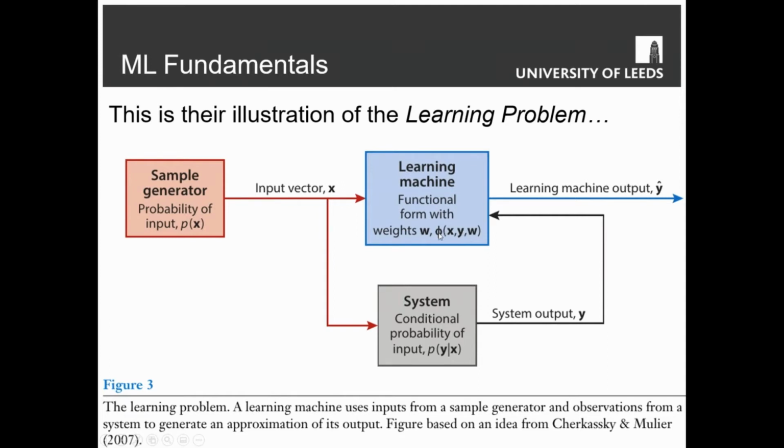And then what we minimize in order to calculate phi is a residual of our discrete Navier-Stokes equations. Instead of solving the Navier-Stokes equations, we just try and find some function which minimizes the residual of those equations, where x and y are given inputs. So x is the input field, y is the flow field, and we want to minimize the residual. Obviously, if we can get a zero residual, then we are satisfying the discretized Navier-Stokes equations, so we can say that's a good approximation. If we have a small residual, then we hope that's a good enough approximation.